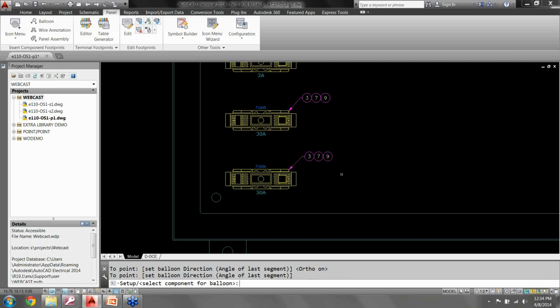Added all the information for the multiple catalogs, so that bypasses that issue. So it's two things that have to happen. You either have to connect the schematic list first. If you're connecting this second, before you hit that OK button, hit that multiple catalog, then OK, and you're done. So it's an easy workaround. It's just getting in the habit of doing it every single time.